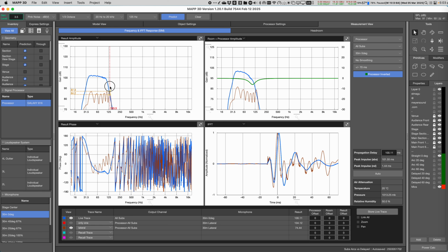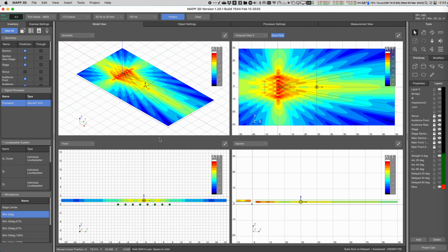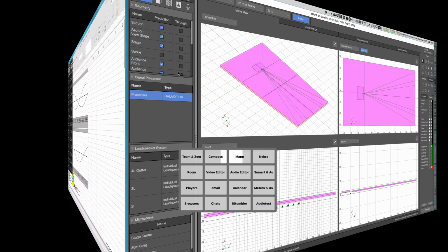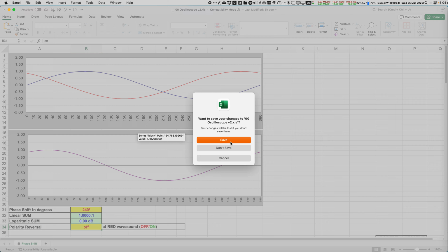And here in the lateral, this is where it's trying to have summation, but it's after the low pass. So the trick then is that you know what is your low pass frequency, and what you will do for your maximum separation is 2/3 of the wavelength of the low pass frequency. That was explained in a previous video. Okay, so now let me go back to 63 and we don't need this anymore.